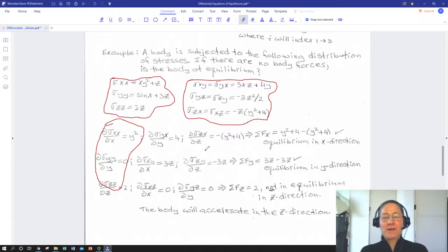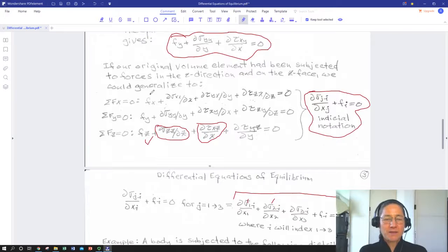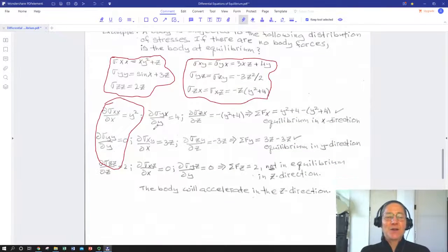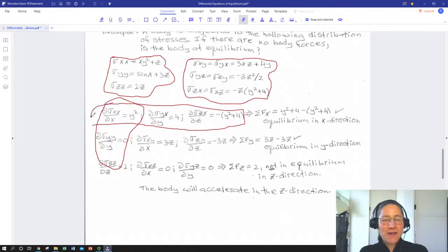Now we combine them. Basically, I like to go back to these formulas that we derived for equilibrium expressions in each direction. The normals are pretty easy, but I have to remember that I'm going to include my shears on the faces in the direction, in this case, of x. So I'm going to look for all my x direction shears. So I have these lined up correctly. So everything on this line is contributing to x equilibrium, and everything on this line is contributing to y equilibrium. Right?